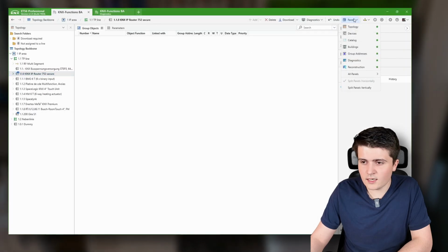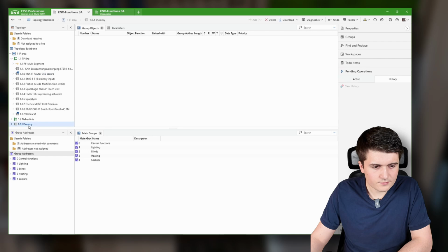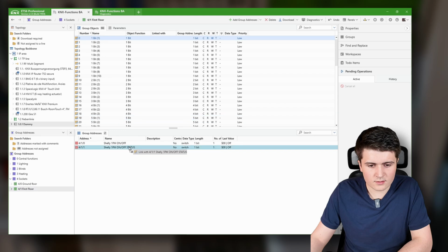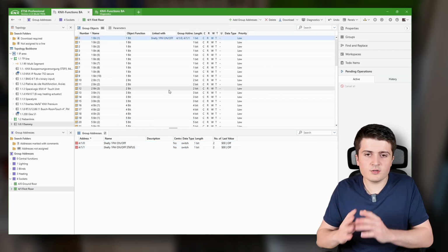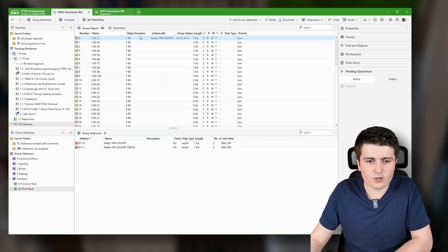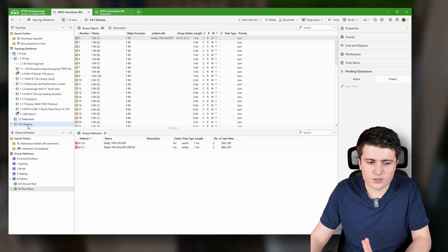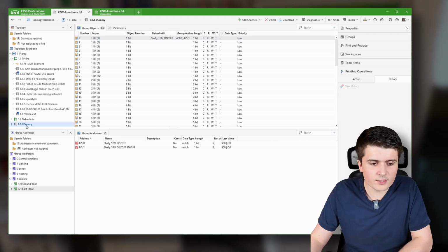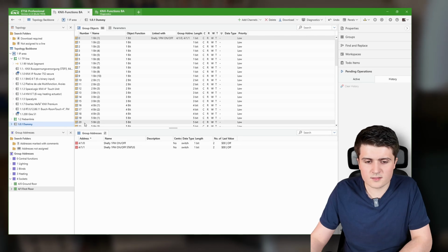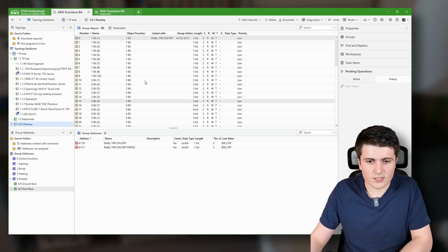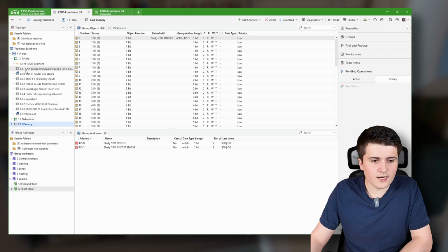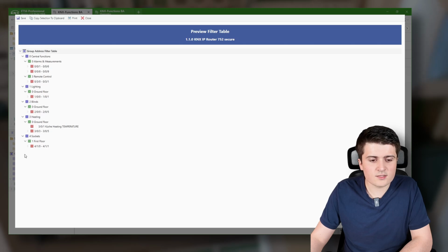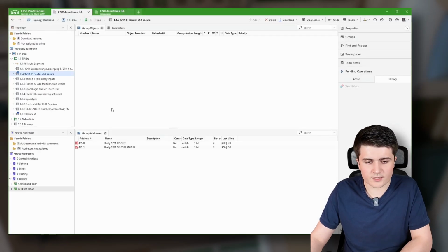But if I now open up the group addresses, go into my dummy, into the Shelly socket here, and simply connect them. It really doesn't matter how you connect them or to which object you connect them, because we don't use this device to program it. We simply need it as a placeholder, a dummy device, so that the EDS knows that this device exists. So now I have added it to the group addresses, and if I go into the KNX IP router, into the filter table, we can see that now these sockets are added here. And this is what we need.